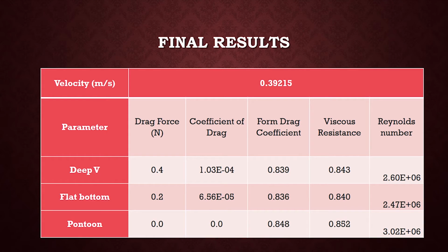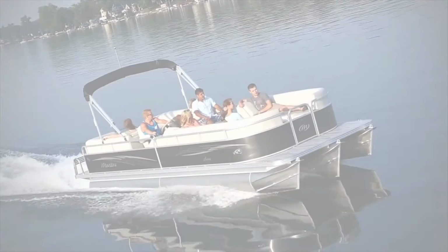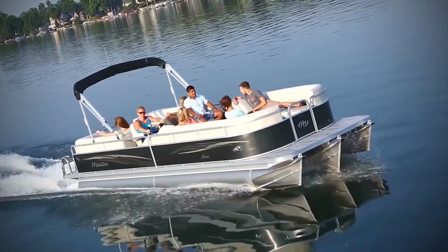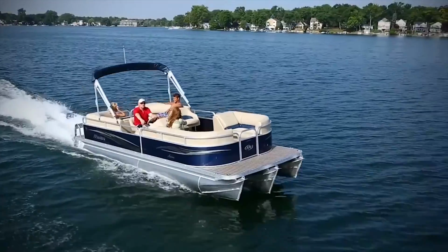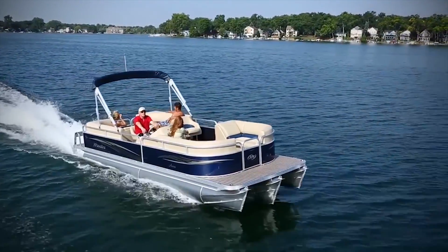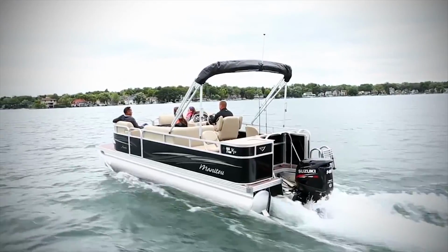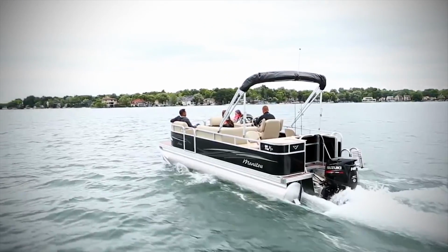However, our fish scale rig was unable to detect a drag force from the pontoon, introducing error in our measurements. Typical pontoon boats are designed to float on top of water rather than be fully submerged, so they will experience less drag in real use than what has been modeled in our experiment.